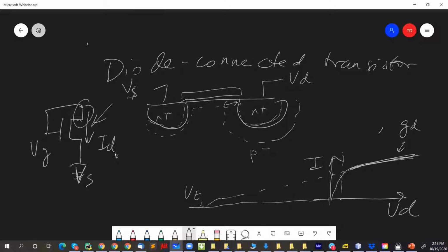Yeah, so if I make the drain voltage higher, the drain depletion region gets wider, and so the channel gets shorter. As the channel gets shorter, either the diffusion current gets bigger because the gradient of density is higher, or if you're above threshold, why does the current increase as you make it shorter? It's because you have a bigger electric field, right? You have the same voltage but a shorter distance, so a bigger electric field along the channel means more drift current for the same charge density.